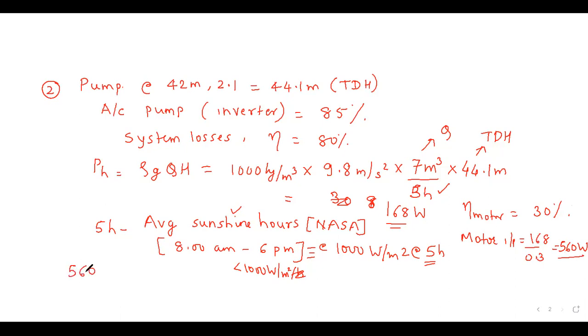So 560 upon 0.85 gives us 660 watt, and then 660 watt upon 0.8 gives us 823 watt.